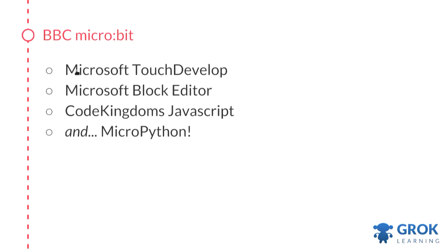So if you've done Arduino, again, I actually really like Arduino, so I don't want to keep hating on it, but the process for the MicroBit is just so much simpler. You download a .hex file, the MicroBit shows up as a USB drive on your computer, you drag that downloaded file onto it, and it reboots, and you have your code running on it immediately. But what the BBC did was, of the 4 options they provide for languages, the 4th one is MicroPython. And you go to the website, you get a little IDE in the browser, and you write Python in the browser.